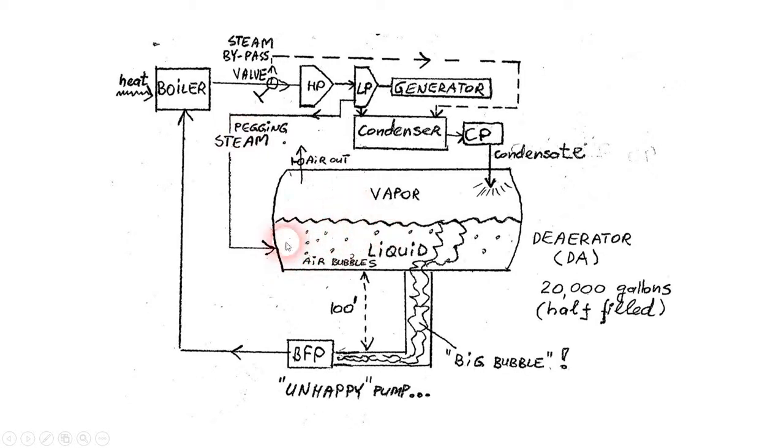As a result of that, the pressure and the hot steam are not available. Cold condensate still goes in. That causes liquid to flash. And then the flash vapor can be trapped into the header, or suction header downcomer, into the pump, and of course, bad news to the pump. Most of you probably know that a pump in cavitation is not a happy pump.